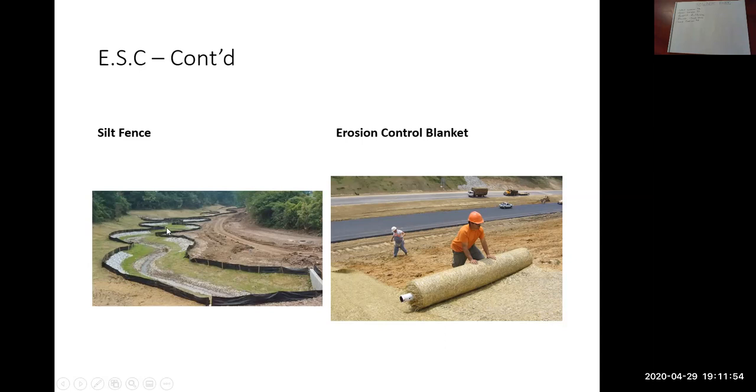So this silt fence is likely protecting this stream here from, maybe this is a haul road here. So if it rains, right, dirty water would flow this way. And if the silt fence wasn't there, it would go directly into the creek and kill a bunch of fish downstream.